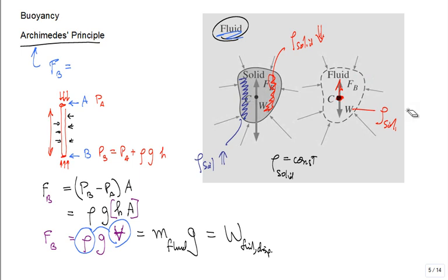Now because the weight does depend on the density of the solid, for this case where I don't have uniform density, it's heavier or higher density on the left and lower density on the right. Will the correct placement of W change, or should W always still be at the centroid?